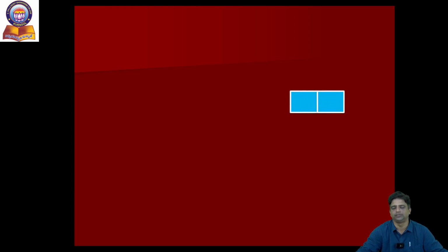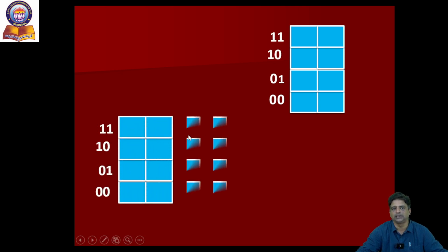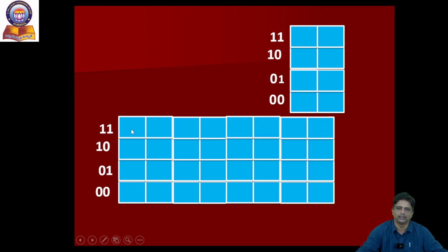What this slide represents is how addressing is done through the obtained address lines. If we have one address line, we can map up to two locations. If we increase the count of the locations, the size of the address lines also increases. But if we increase the size, not the count, of the locations, we need not increase our address lines. The size indicates the capacity of data, the count indicates the addressing lines.